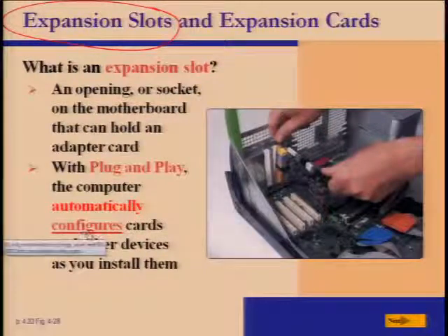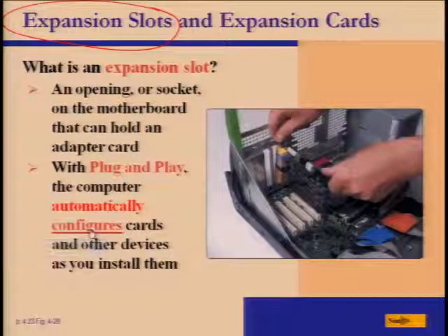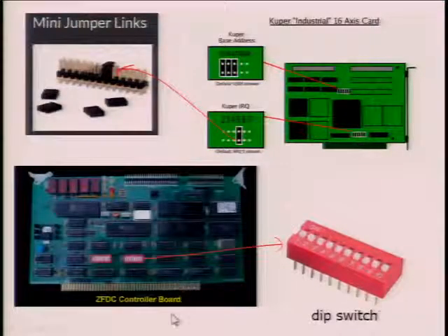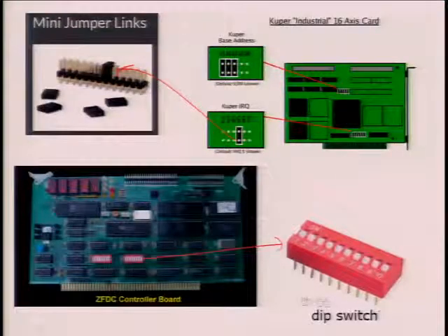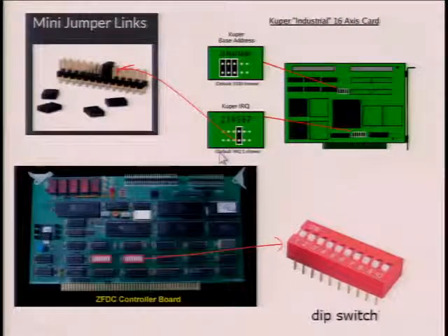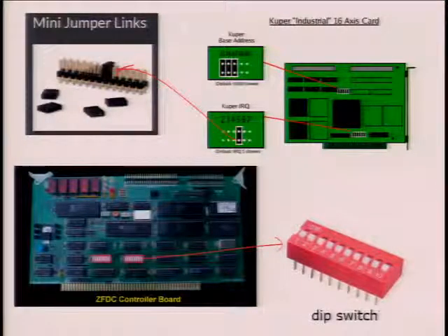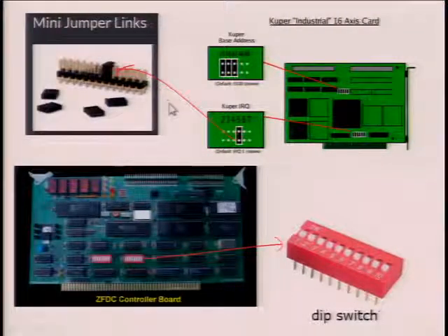I will just show you another two slides. What are those things that you need to do? Typically, on the new card, they will give you something like this DIP switch, or sometimes they use a jumper connector. So they will advise you to set a certain configuration. With a different jumper location, you come out with a different setting.